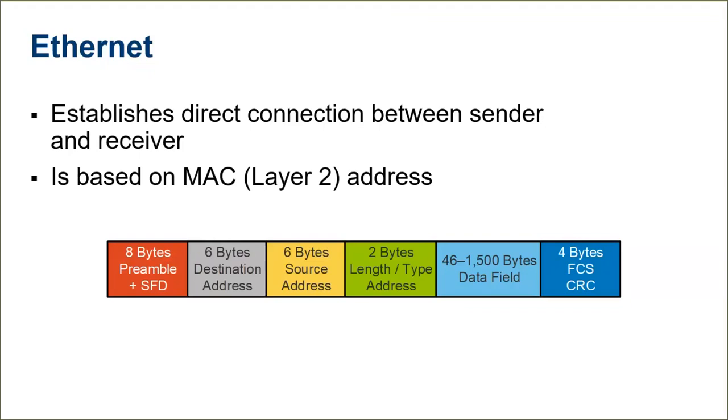The preamble up front is a signal startup time used to recognize that the frame is being transmitted. Because each station on a network has its own oscillating clock, all the communicating stations must synchronize their clocks together. The preamble consists of 8 bytes of alternating ones and zeros, ending with 1, 1.